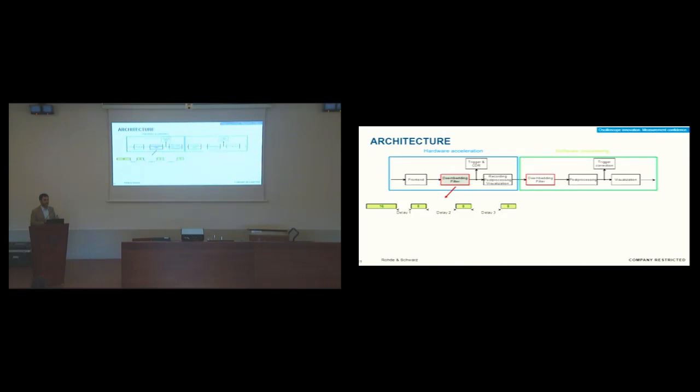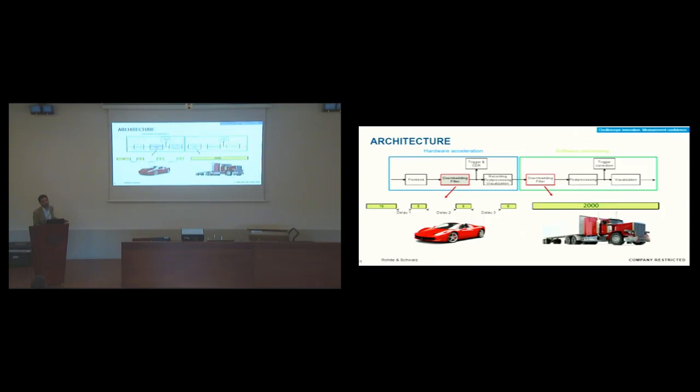So the impact on the speed of the oscilloscope is not really strong. It's very little, and we'll be able to perform eye diagrams and some other measurements with very fast acquisition, and also triggering on this corrected signal. So we are really triggering on the signal we are measuring at the transmitter point, in the DUT plane. So this is very fast. As I told you, doing it by software is really slow.